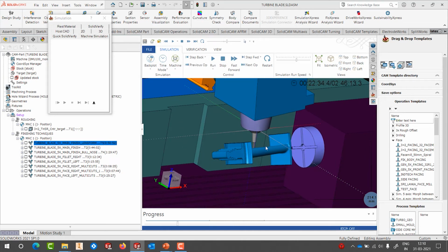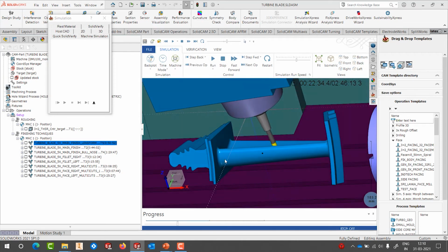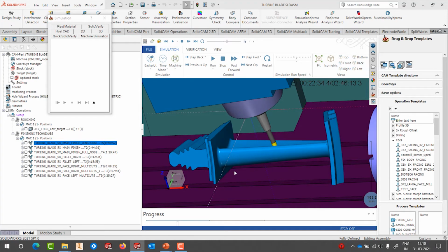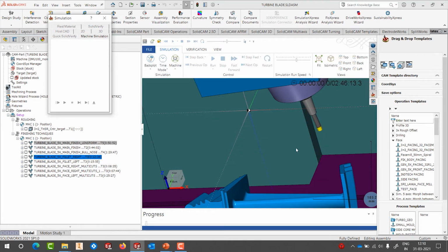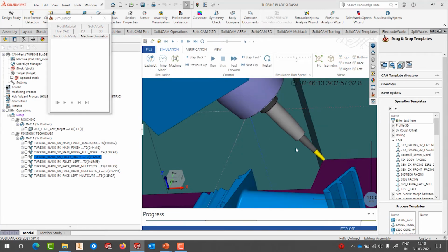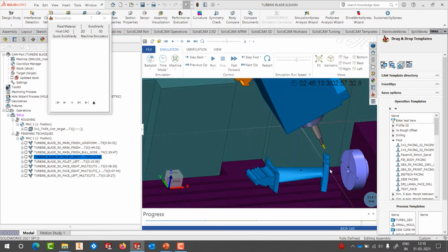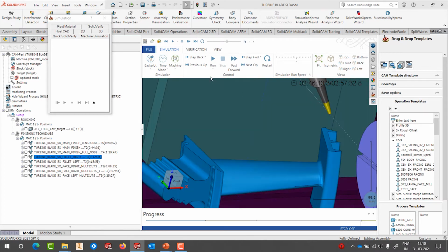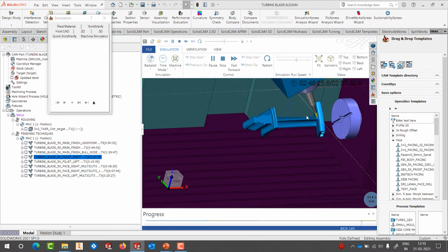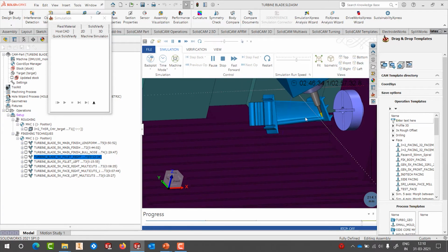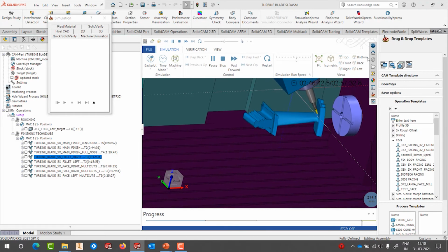Right, now the biggest challenge in machining such parts comes when you are trying to machine the fillets, the base or the root fillets, what they call, as well as the base surface. So here I have got machining that's using a taper ball nose, and we are cutting the root fillet. You can see what actually is happening in this case.